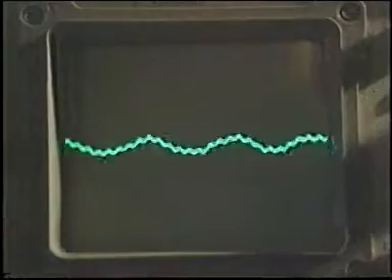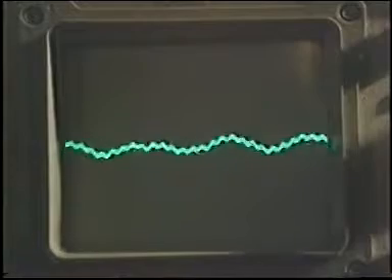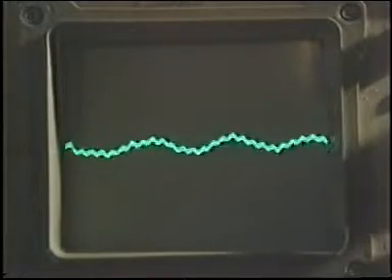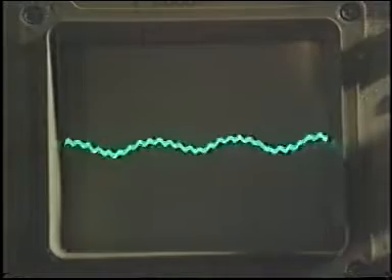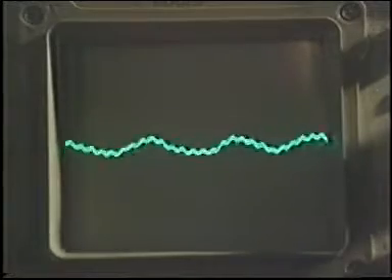Well, if you look at the time domain waveform, you can see the residual effect of that high frequency interference putting the ripple on the waveform. There's one way we can get rid of that. We know what the interference frequency is because we've been able to measure it from the spectrum analyzer. So I've designed a notch filter, which is a very, very sharply tuned filter, right at the interference frequency.